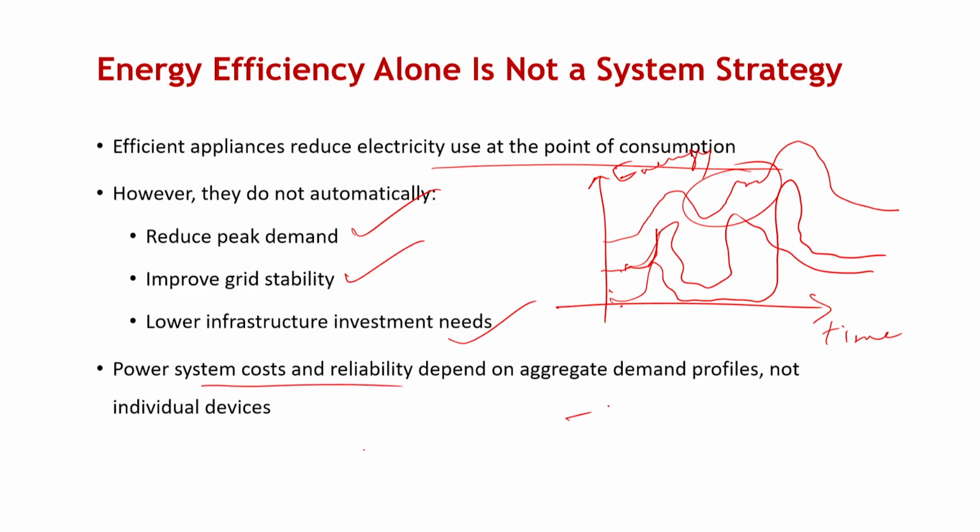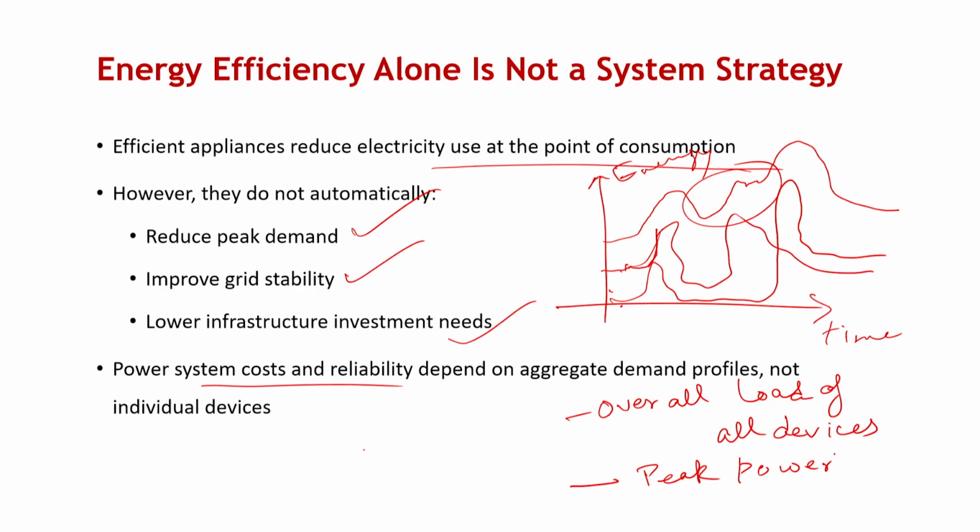It will be determined by the overall load of all devices put together, and also by the peak power, because you want a reliable system. Since you want a reliable system, you always have to design it as per the peak power requirement.